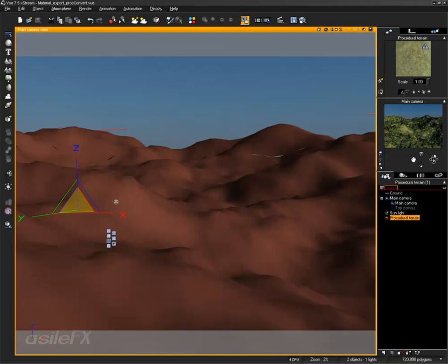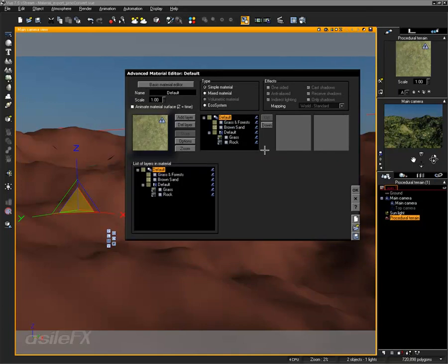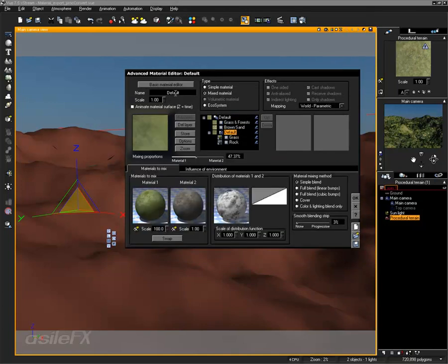And now what we can do is convert this over without that duplicate. And this could also be caused by the material naming within the material, one of the reasons that caused the crash. So one thing I am going to do is modify the names of the materials.